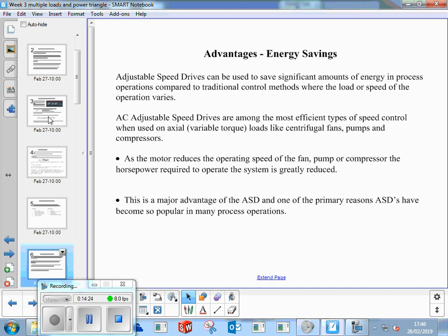But they'd vary anything from the bottom revs to between two limits. They were constantly variable. But the cost of the brushes and the maintenance and the rewinds that we had to do, and we replaced two machines with inverter drives and induction motors and never touched them again the rest of the time I was there. So although there's that expense of buying quite an expensive drive, the motors aren't particularly expensive. That saving in maintenance is significantly higher, and you're saving breakdown time as well.